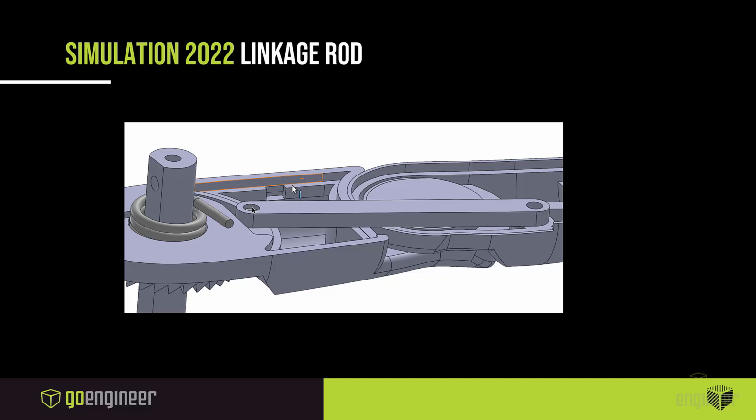All we need is 2 pins, and you need to know the geometry of your part and the material of your part. It is very straightforward. And I actually did really need to use this for this model because when I ran it for the first time, this linkage was costing me an excess of 70,000 elements and was increasing my solve time drastically because this was a dynamic part. I was saying that there were sliding faces in between. I had to make sure the mesh was good.